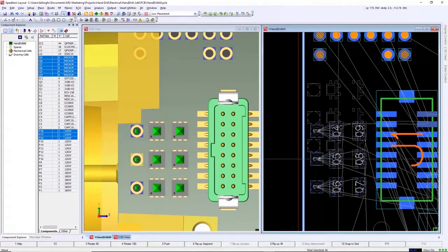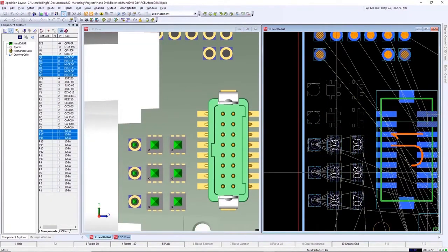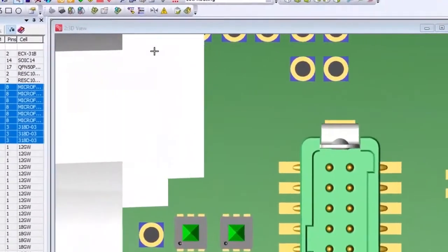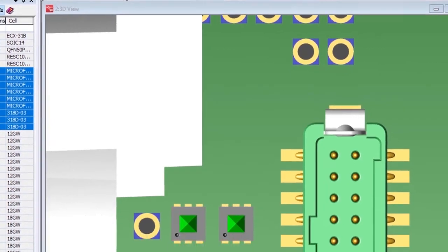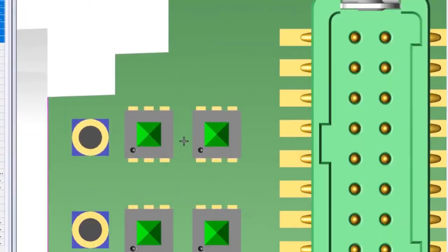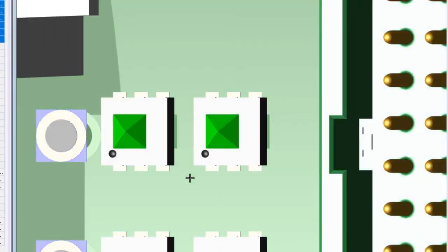Lastly, we'll adjust the placement of our FETs and wire soldering holes for optimal placement. Using DRC checks is necessary to make sure our PCB can be manufactured and assembled properly, but these are based on minimum values. There are times when we need to know distances between 2 objects for other reasons.